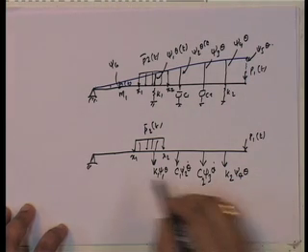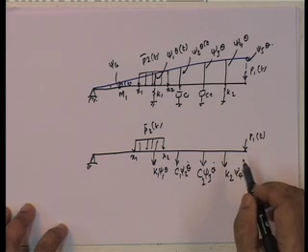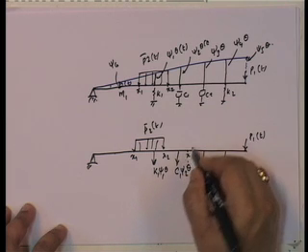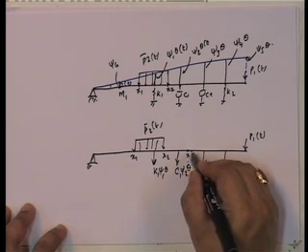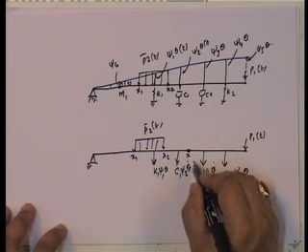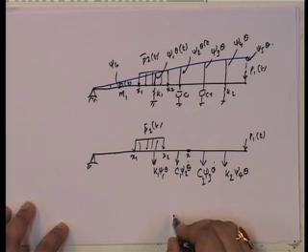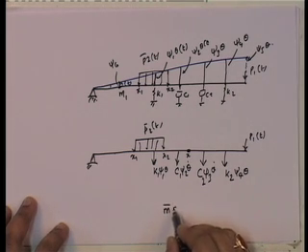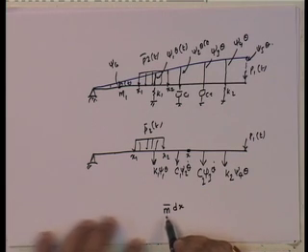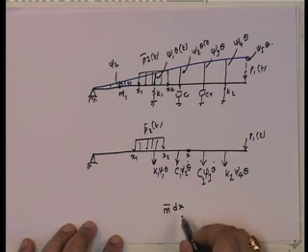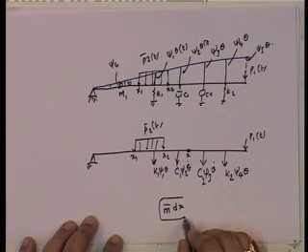Note that every point is being moved. Let us take a mass at a particular point, and let us call it x. The mass at that particular point over an infinitesimal length dx is going to be equal to what? The mass is going to be m bar dx, because m bar is the mass per unit length and dx is the length.